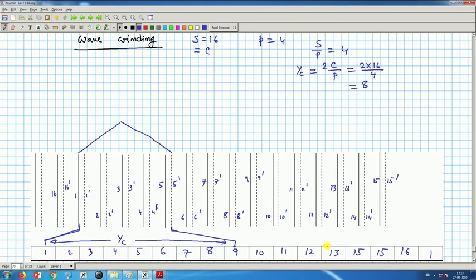This is the first coil. Then the next coil I will connect in series. Where should I start the next coil? From this commutator segment dictates me the slot number I will go. So, 9 I will connect to the next coil, and its span is 9 plus 4, 13 dashed.